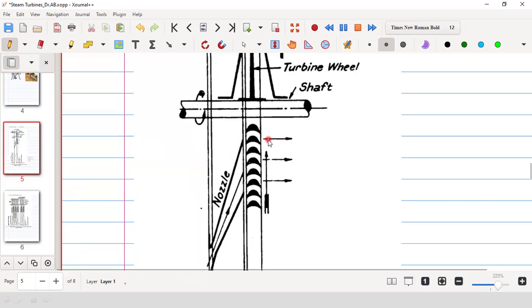Before that, it must have a tangential component, otherwise it will not do the work, isn't it? After that, it has already passed and there is no work to do on the blade, so it is exiting simply as axial velocity. If at the exit there is some axial velocity, that means all the axial component of velocity we have not converted or transferred to the blade.